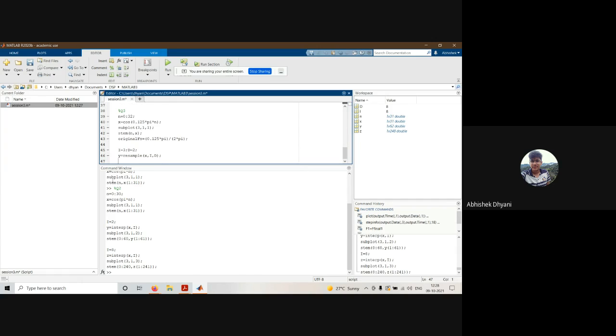And we can similarly calculate the desired f s we will obtain after doing this sampling rate conversion. So the desired sampling frequency will now become the original one multiplied by this factor of I by d, right?